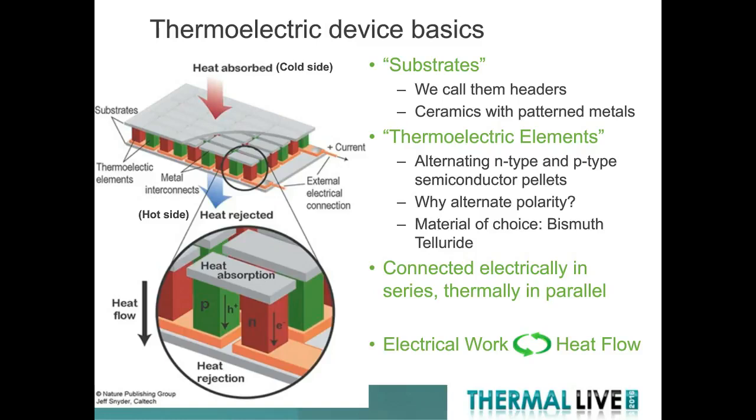So you can think of those individual thermoelectric elements as a group being connected electrically in series, but thermally in parallel. And in the end, they're heat pumps, so they can convert electrical work to thermal work and heat flow, and vice versa, in the case of energy generation applications.